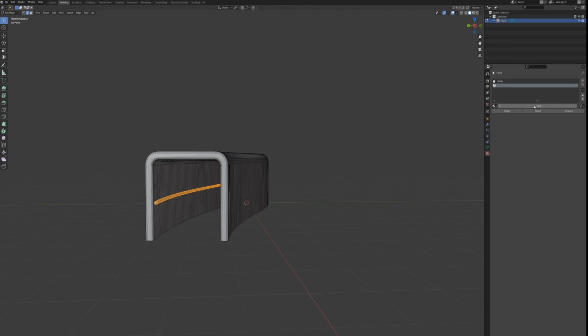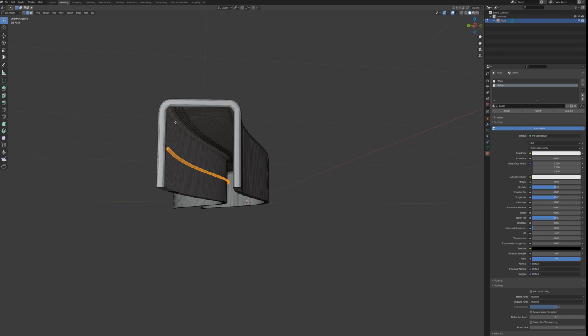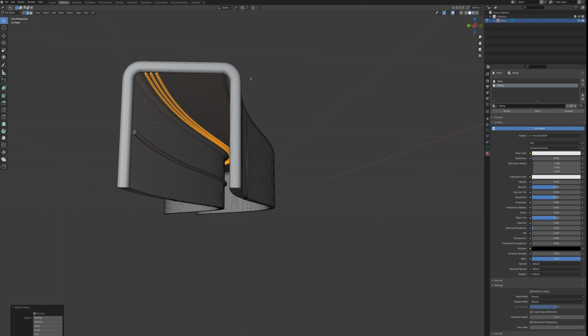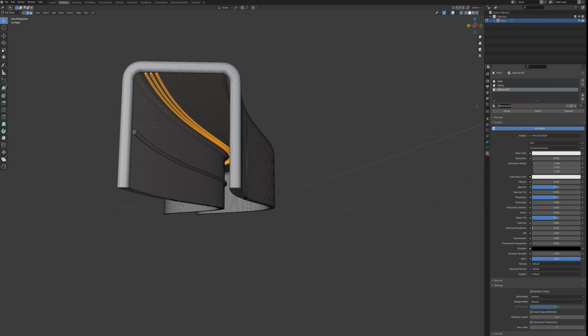Okay, I'm going to clear my selection and hover over this railing and press L. Make a new material. I'm going to call this Railing and Assign. And then I'm going to clear my selection, hover over these pipes on the roof here, L, L, L, and I'm going to make another material, new, roof pipes, and Assign. And now I'm going to move on to the UVs.